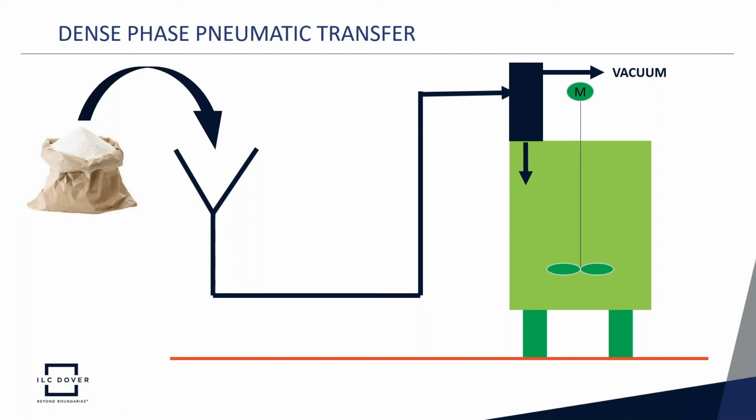It also has the benefit of being able to have a number of arrangements to charge the powder into the transfer system from a range of different bulk containers, from bags to drums of all sizes. However, there are some disadvantages of dense phase transfer in this application. The first is the limitation in achieving precise charge weights because of powder holdup in the entire transfer system.